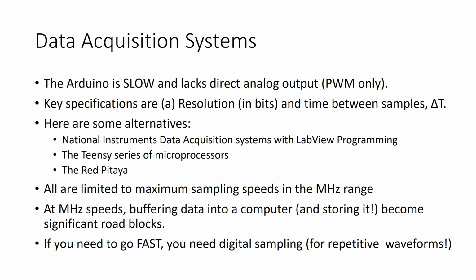In other words, if you have a signal that will cover some voltage range, and you know the smallest change you want to detect in that range, that will tell you then that if you manage to match the entire voltage range to your detector system, which by the way takes a bit of thought, it'll let you know how many bits you'll want your conversion system to convert into in order that you have at least a bit or so of change for the smallest change you need to detect.